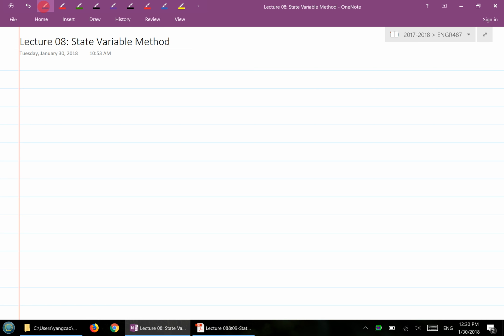Okay, so we're going to shift our attention to a slightly different direction now. In previous lectures, we had a discrete sequence, and you derive the pulse transfer function for either open loop or closed loop, right? And then you can design a simple digital PID control around this pulse transfer function, or around this sampled-data system.